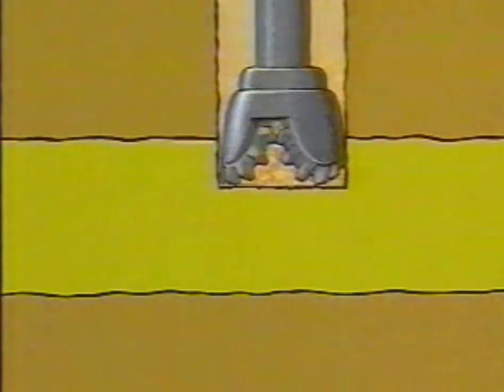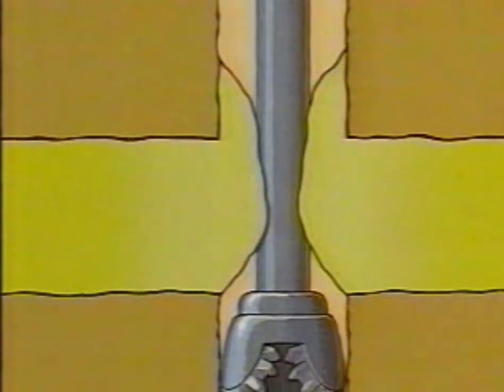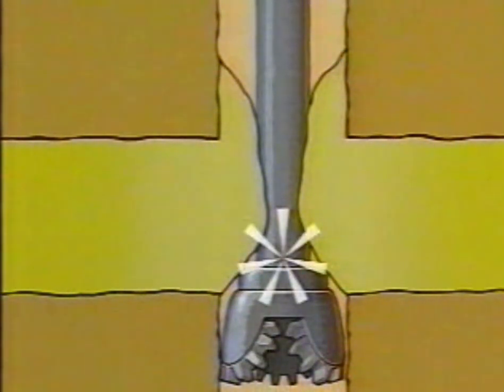Certain formations, such as gumbo shales, which contain a large amount of bentonite clay, can react with the mud filtrate, causing it to swell and subsequently invade the wellbore. Continued invasion of this kind results in clay balls and mud rings, which can build up and eventually make contact with the drill string, causing it to jam. The potential risk for stuck pipe is increased as the pipe is tripped out and the BHA becomes trapped by the mud rings. Let's look at that again.